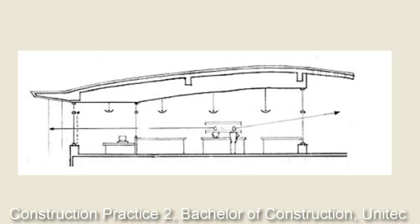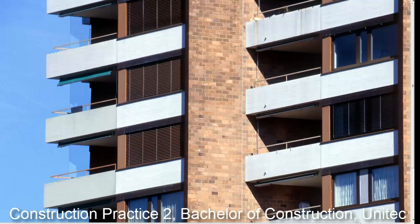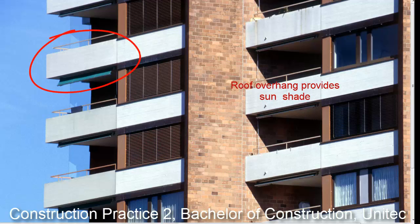We get a lot of heat gain in through the north facing side of a building, and a simple passive solution to reducing heat gain in a building is to create a roof overhang, or an apron to the building facade. So here's a couple of examples here, just showing a big overhang, which can give us some sun shading. There are other simple passive solutions, and we'll explore these in the lecture, of some passive design that utilises overhangs to produce shading within the building.